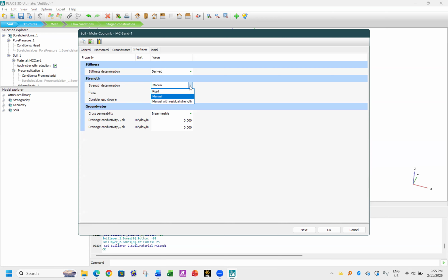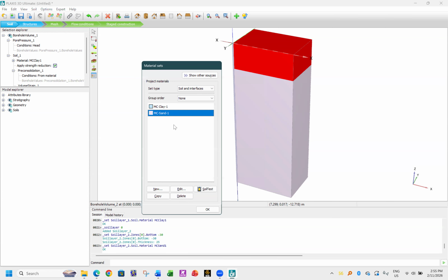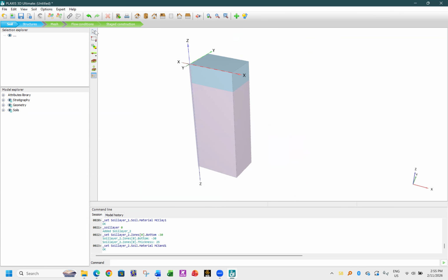Oh no, it's the main one. Sorry, main one, so 0.7. Okay, we'll keep it this way for soil structure interaction, because there will be sand inside, and the solid material is concrete inside this one, because we are going to get the bearing capacity of the pile. Okay, now we have created the soil.